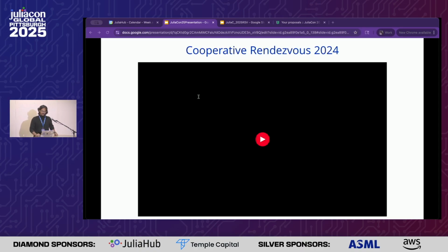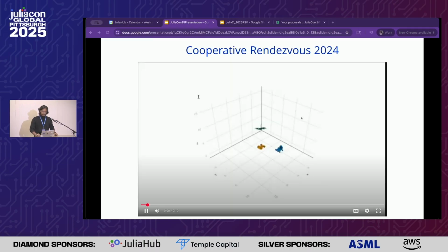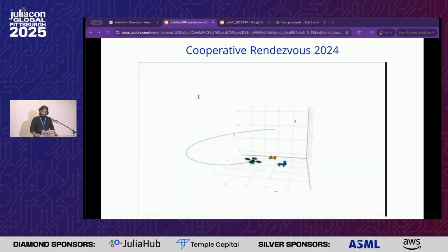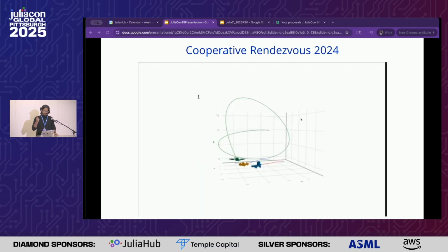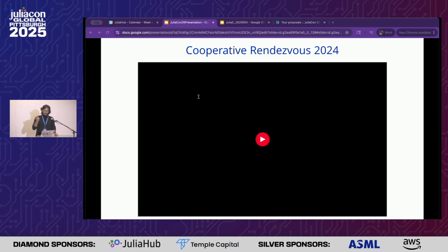So this was my presentation last year. Just a quick recap: we have an autonomous rendezvous of 2 ground vehicles with varying dynamics. They don't have the same dynamics, and a quadrotor utilizing a polynomial trajectory following geometric controller. So the quadrotor hits 3 waypoints before landing, and it triggers a cooperation between the ground vehicles, at which point they start to receive the time to go of the quadrotor every second, and they just autonomously achieve rendezvous. There's no manual control. It all happens by itself.